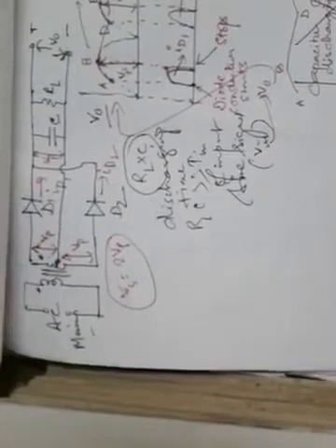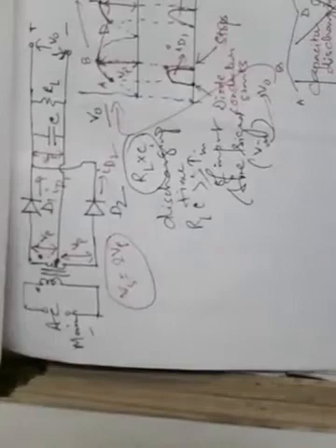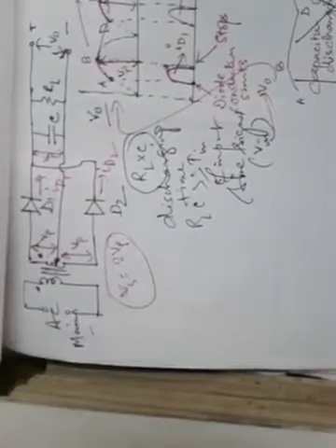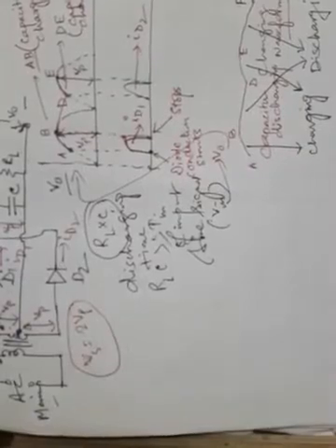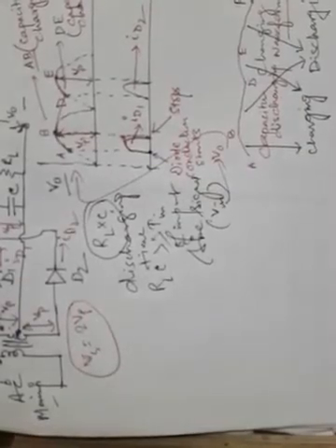So whatever charge is drained off during the discharge mode will be once again regained by the next immediate conduction cycle by any one of the diodes D1 and D2, during which the capacitor will only take charge. And so this is what I had to tell you about the use of a shunt capacitor input filter with the full wave rectifier.